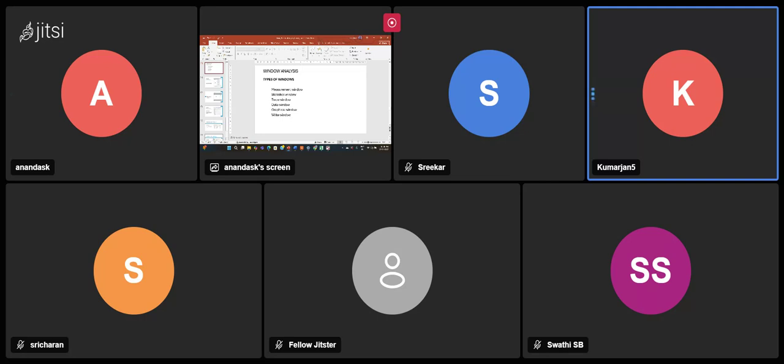Mention this write command and you can examine the values that are popping up. You can pass some variables in a format and print them in the console. With the help of CAPL scripting we can print the values and check whether they are popping correctly or not. With that value we will know whether there are any DLC issues or any error frame issues, or whether any message event is not being processed because the correct frame is not properly processed. All these things you can see in the trace window.